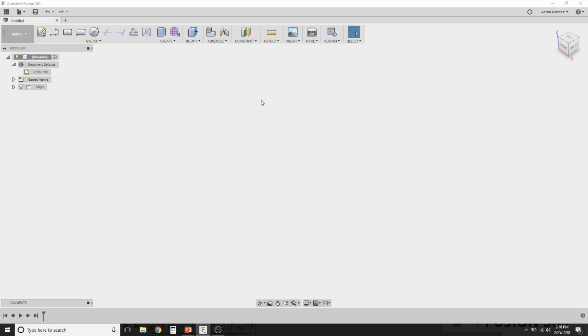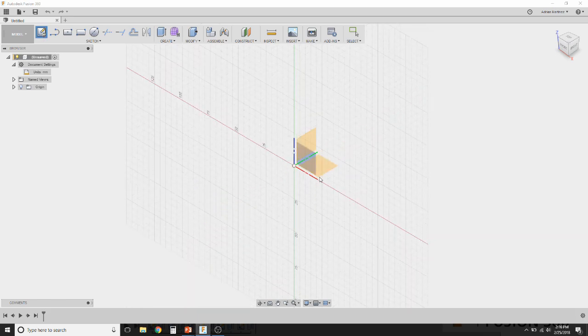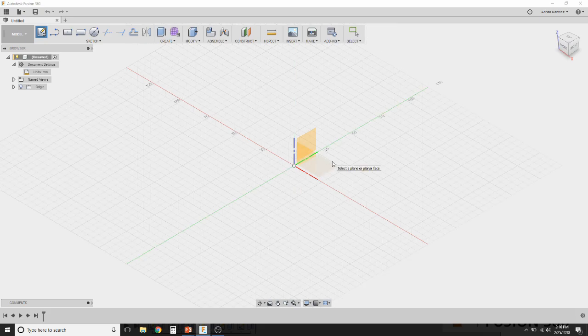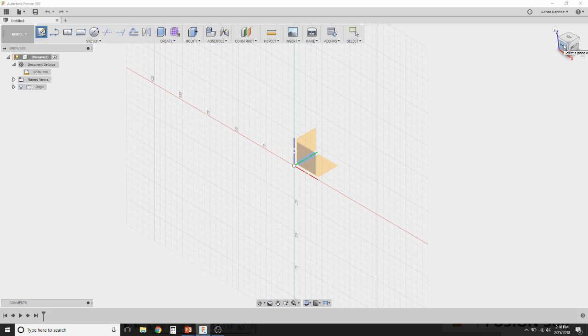All right, so let's go ahead and start a sketch. You're going to hover over the Create Sketch icon, click on it, and then you'll have this set of flags that pop up, and these are basically your origin points. And if you look at them, each plane on the origin is aligned with your view cube. So you have a front plane, you have your left and right plane, you have a bottom plane.